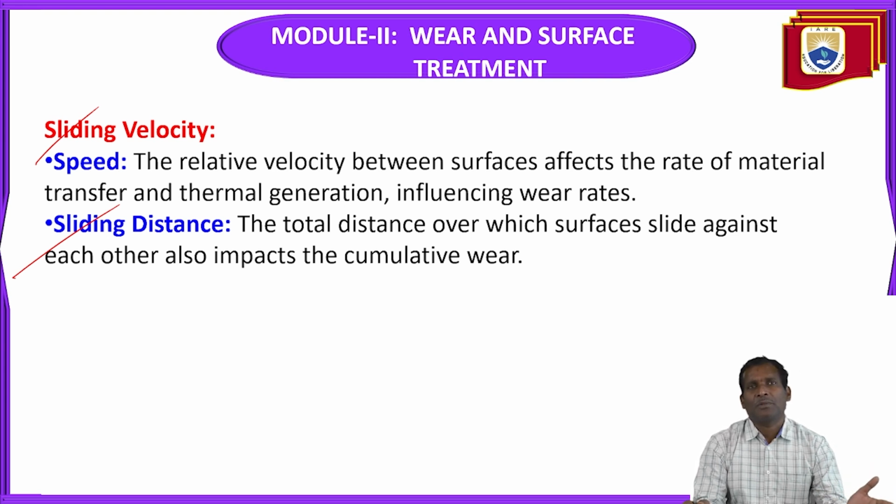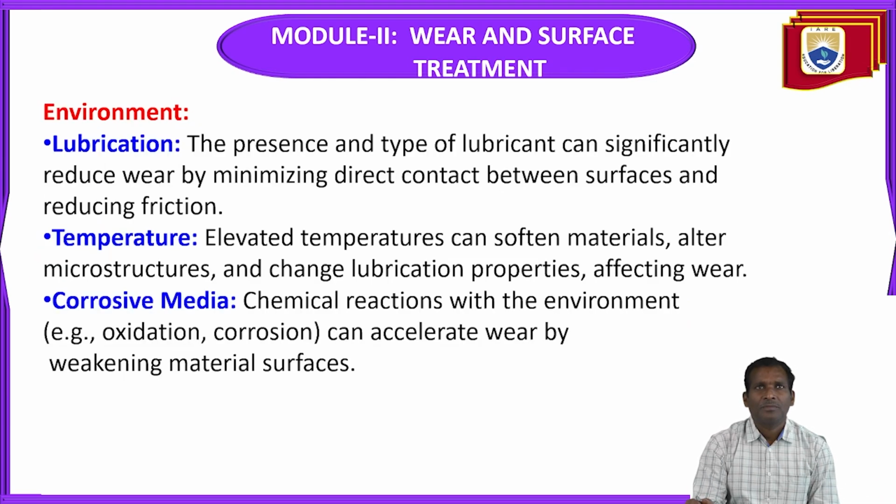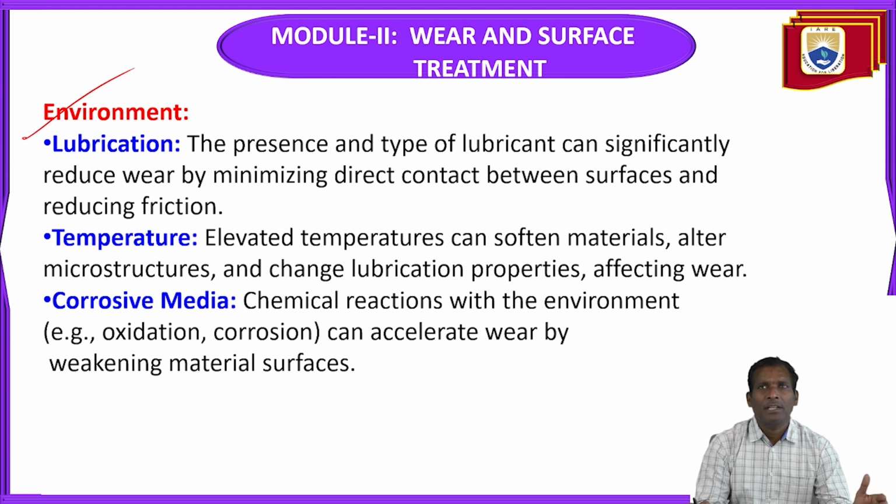You can observe this in the pin on disc experiment. The total distance over which surfaces slide against each other also impacts the wear. So next, environment. This environment is lubrication. The presence and type of lubricant can significantly reduce wear by minimizing direct contact between surfaces and reducing friction.